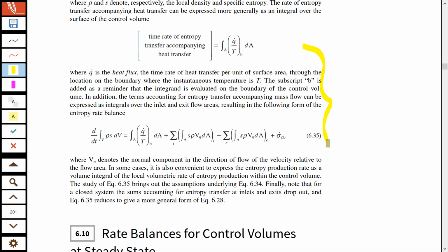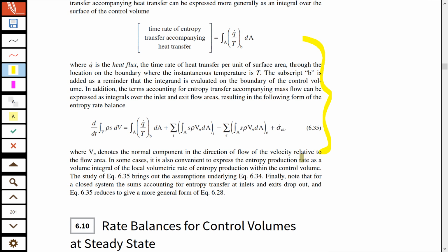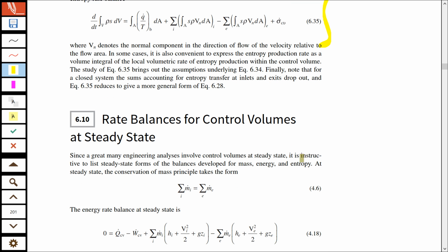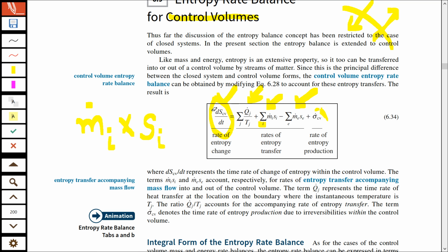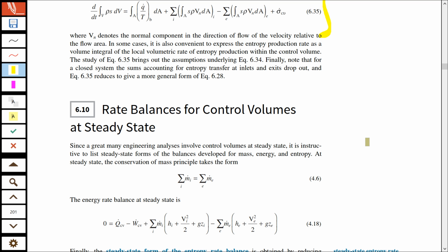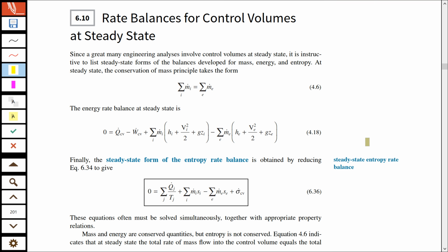These equations are not the focus of this course. They are needed in serious design for mechanical engineers, and we are focusing only on basic principles. So we want to get as many basic concepts from this course as possible. If you now look at that equation again for the control volume, and you want to consider this in the steady state, what will happen? In the steady state, the left-hand side will be 0. So you can rewrite the right-hand side by writing everything related to the inlet on one side, and everything related to the outlet on the other side.